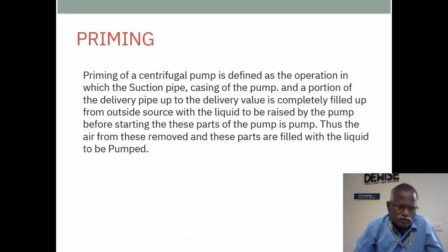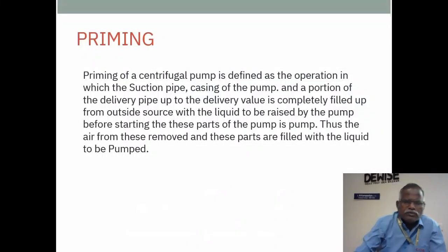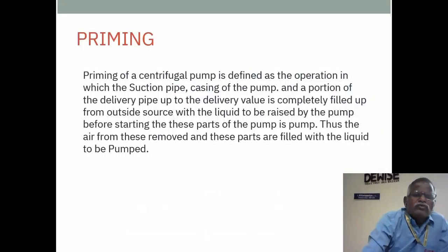This is called priming. Priming is nothing but removal of air from the suction pipe, casing of the pump, and portion of the delivery pipe. It's called priming by using water.